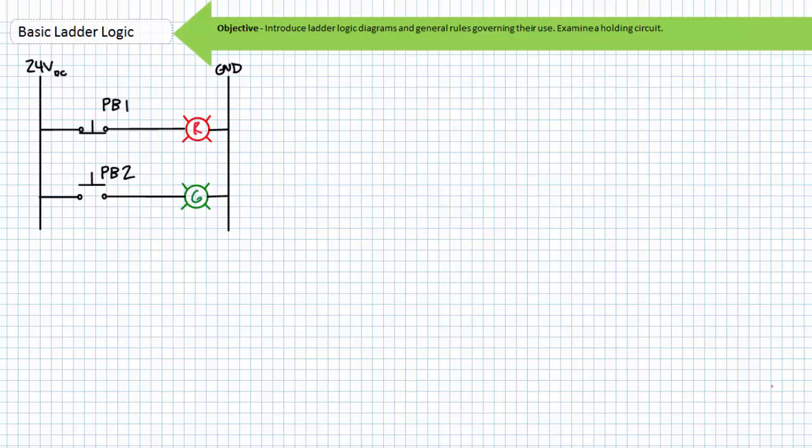This means normally closed push button 1 is closed, and normally open push button 2 is open, as implied by their titles. The normally closed push button 1 keeps the red pilot lamp in the energized state. The normally open push button 2 keeps the green pilot lamp in the de-energized state. The natural start state for this system is therefore red light on, green light off.